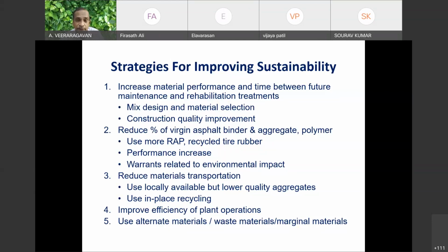Yes. So now, if you do that stabilization, you should be able to predict what will be the performance of a material which is improved. Second, you have to characterize the material. Find out the property of the material after it is improved, which means you have to do a mix design. Third, in laboratory, we can do anything and everything. Take 1 kg of soil, 2 kg of soil, 5 kg of soil, precisely measure the water content, add it, mix it by hand, compact it, and then get a density.